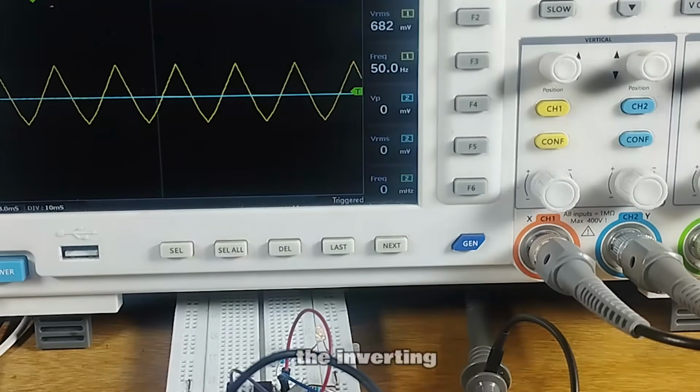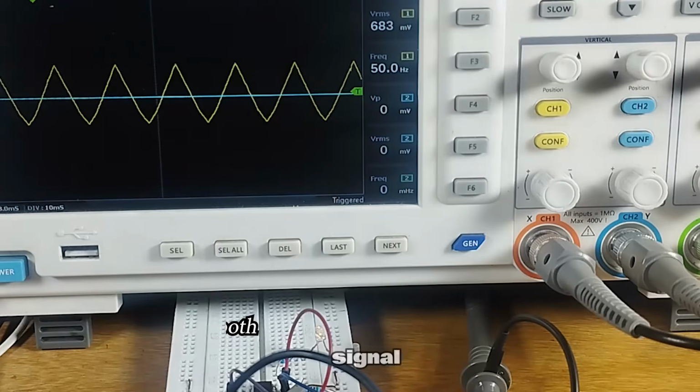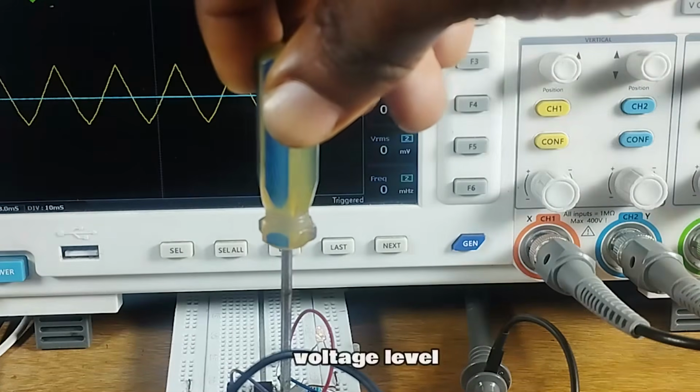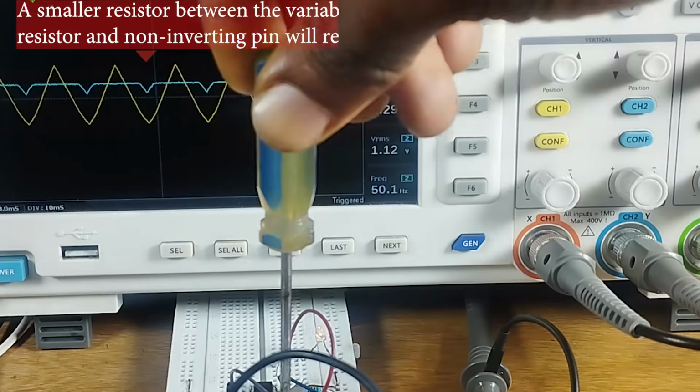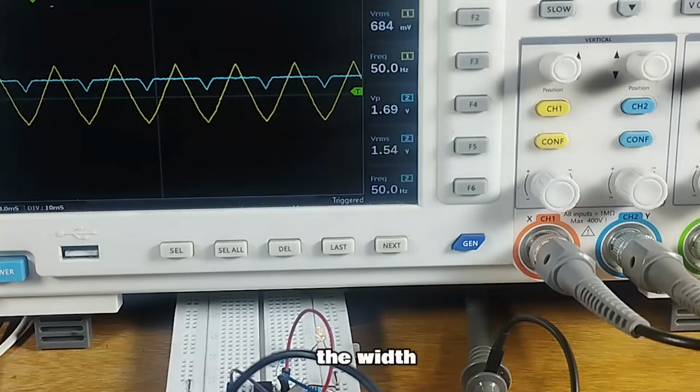On the inverting pin we have our sawtooth waveform signal, while on the non-inverting pin we have our DC signal, and we can see that the level is 0 volts. When we turn the knob, the voltage level changes and it increases. The higher it goes, the width of the output changes, and that's because we are changing the point at which the output is triggered.